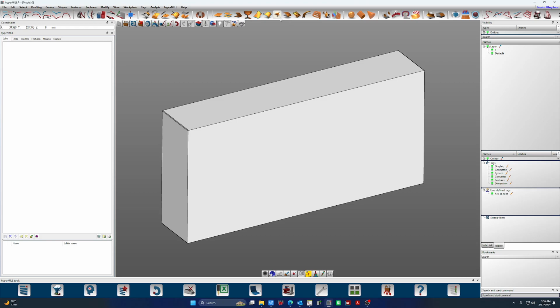You can select a bunch of different pieces of geometry in wildly different points in 3D space and use some basic weighted tools depending on their relative position or tangencies, and it will give you a surface 99.9% of the times. Now that surface might be so bizarre you can do nothing with it, but if you're really trying to get a surface created between several pieces of geometry, even geometry that's not connected, filling will give you something.